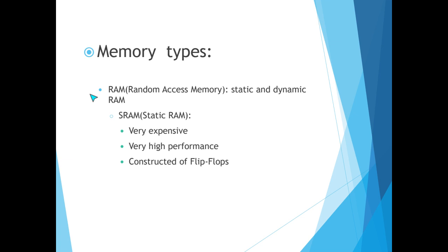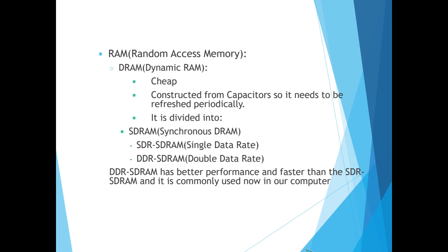Static RAM is very expensive and has really high performance, and it is constructed of flip-flops. But dynamic RAM is cheap and constructed from capacitors, so it needs to be refreshed periodically to charge and discharge the capacitors.